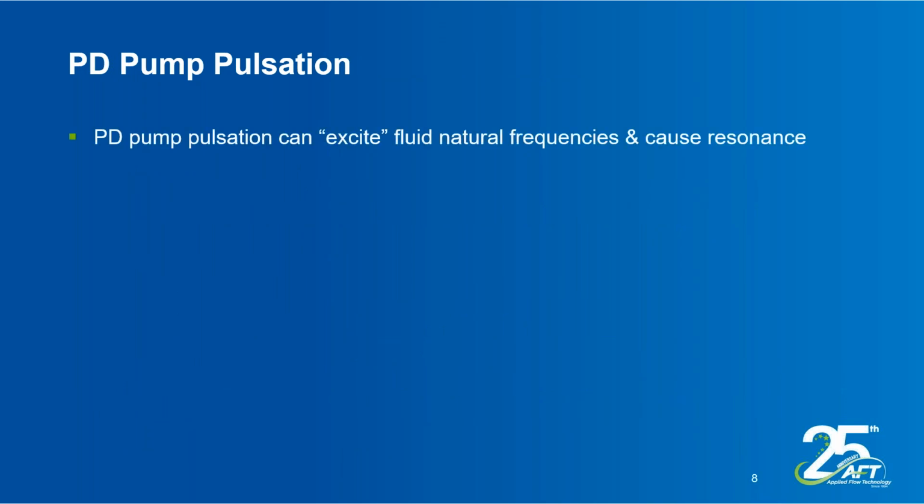So when you're dealing with pulsation from positive displacement pumps, the oscillating flow through the pump can be at the natural acoustical frequencies, and that will cause acoustical resonance, which can tear apart your system.